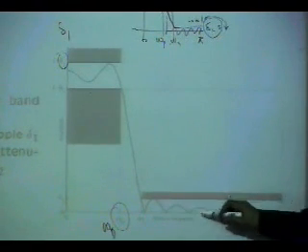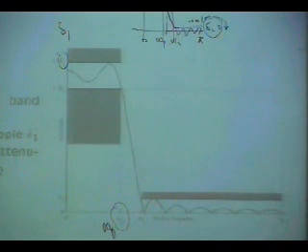Your frequency response should never go above delta 2. So you have to give all these things. These are the design parameters. Once you are designing a filter, you need to specify delta 1, delta 2, omega stop, omega pass.